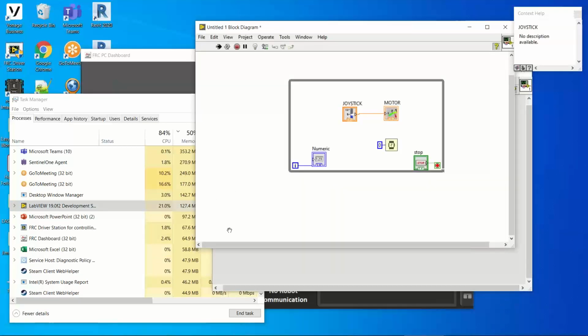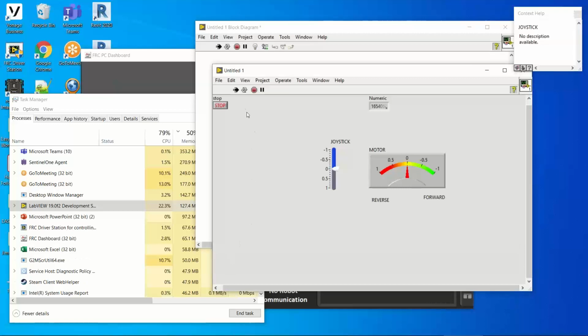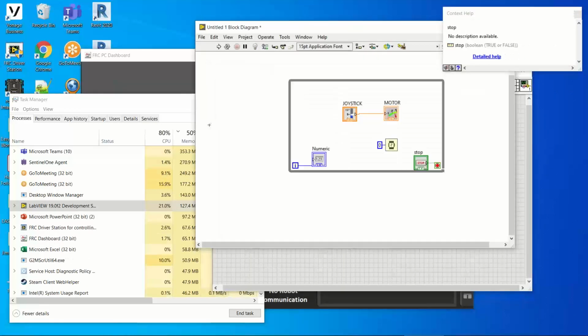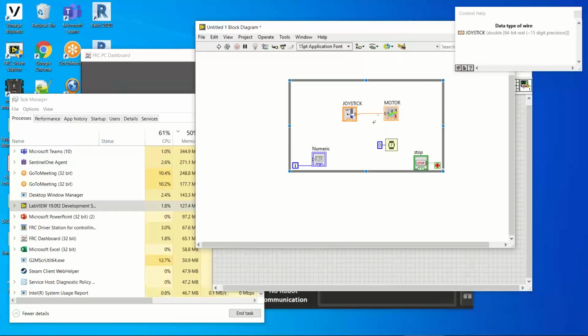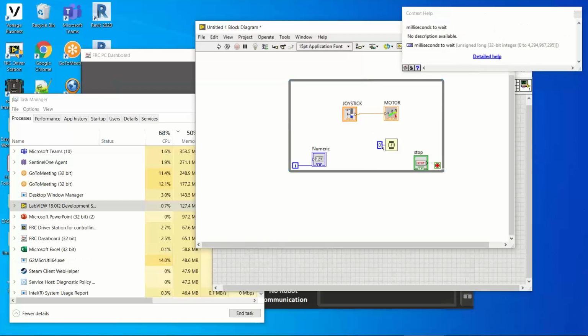So the point I'm trying to make, and hopefully you'll get the point if you do this on your own, for manual controls, I want a relatively slow update rate. And so that's why I usually do a 55, anything between 50 and 70 as far as the delay time between running a loop.